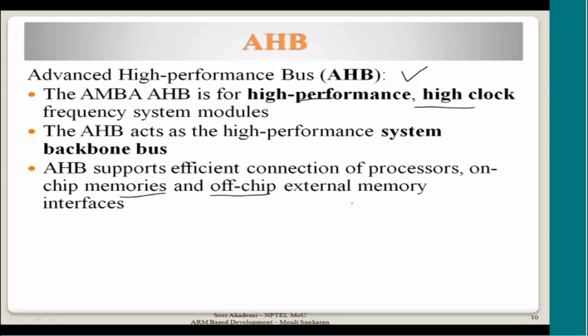So these are the different processors in the system, the SoC. When I say system, it's SoC, because these buses are going to be inside the SoC. AHB supports multiple masters in the system, so you can have multiple processors, and they are all connected to the AHB bus.